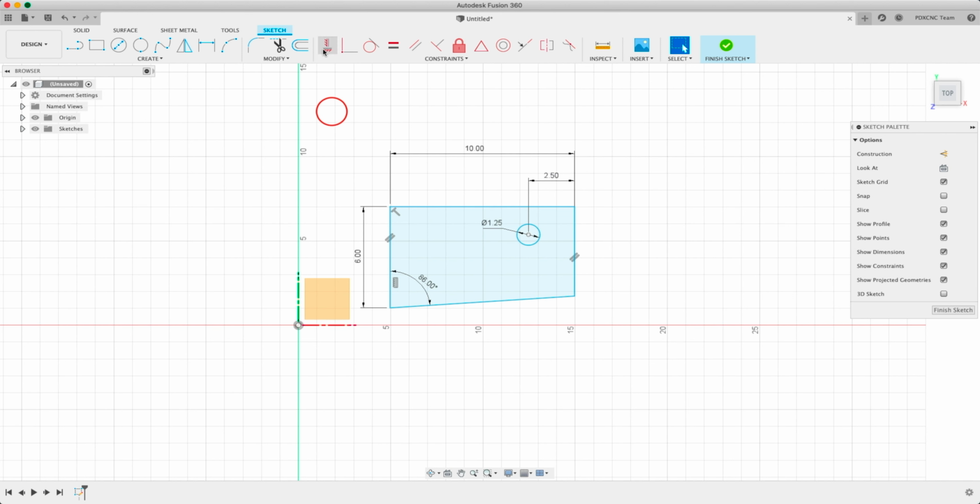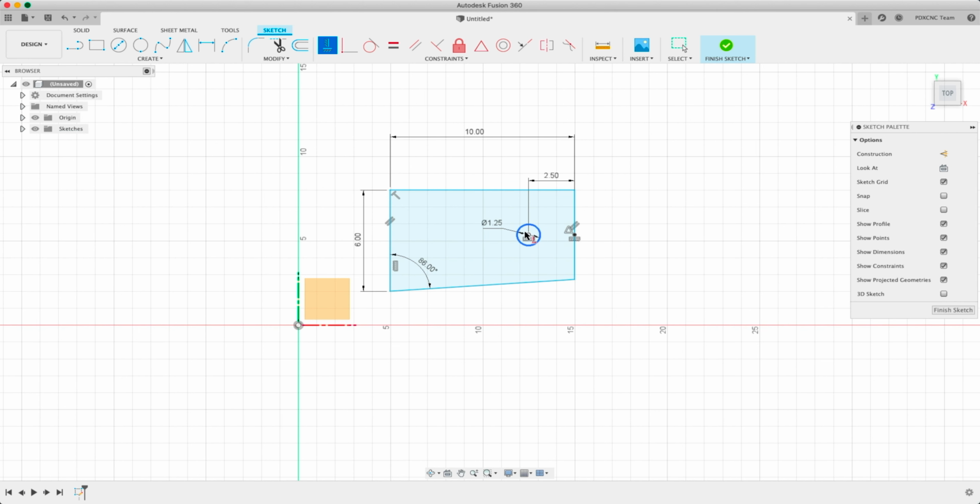And I actually want it to be centered on this wall over here. So I'm going to click horizontal and then hold shift on the keyboard. And you're going to see a little thing that pops up and allows you to select the midpoint of this line. And then I'll click here. And so now we've said I want a horizontal line that's invisible between here and here. That's a little bit of an advanced trick, but I really love that and use it all the time.